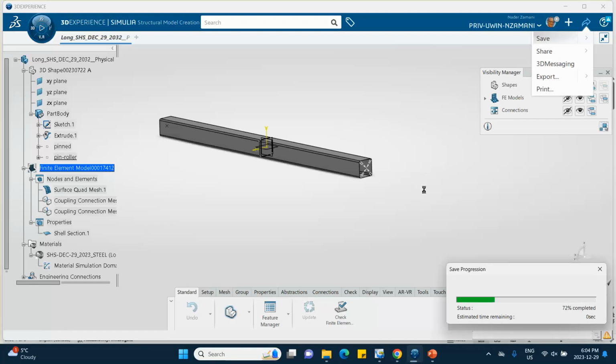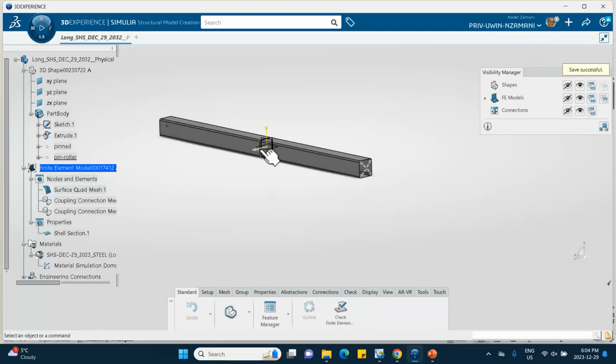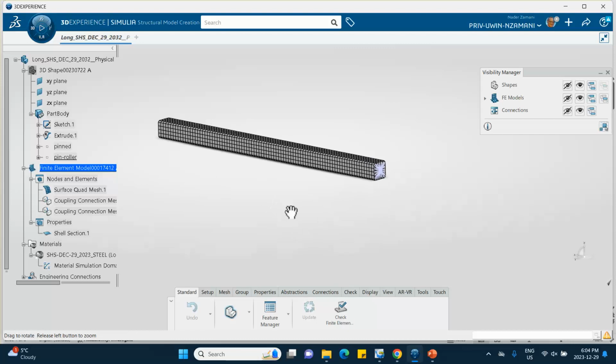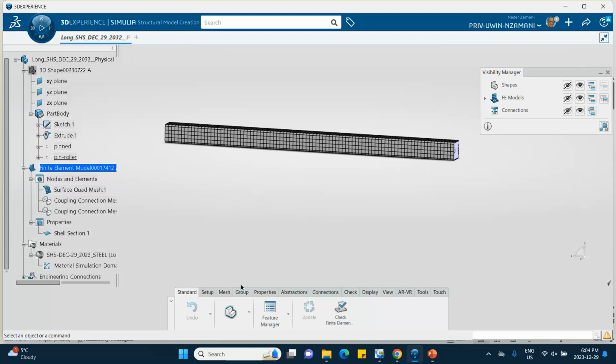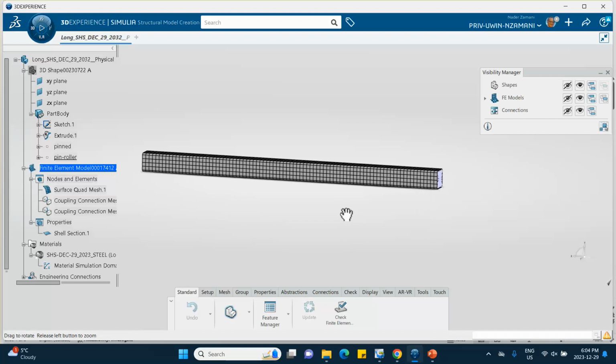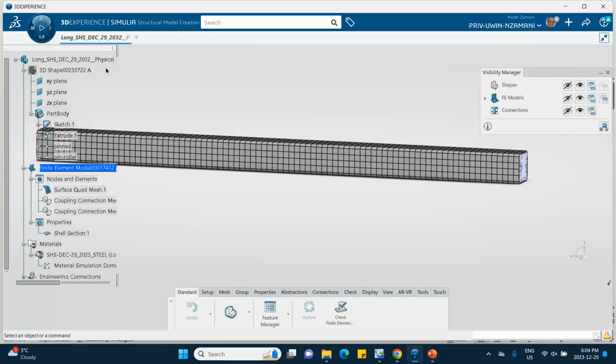Now, what I want to do is also create my group of elements at this middle piece. Right now I don't need it, but when it goes to a static step, I will need those. So first of all, show me the elements. Don't show me the part. I want to create my nodes in the middle, exactly in the middle. The problem is that if you say don't show me the part, then it will not show you those planes either. So let me say, show me the part, I know where it is.